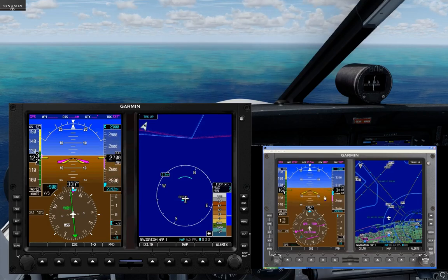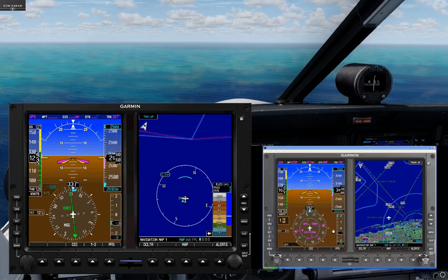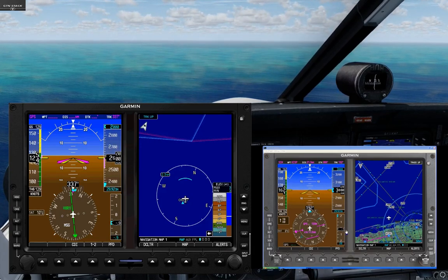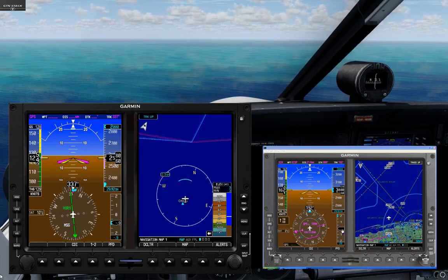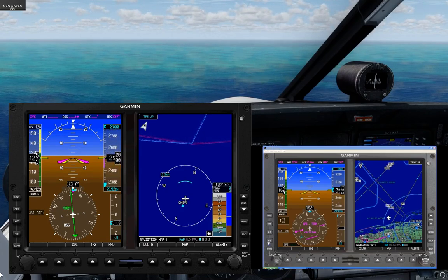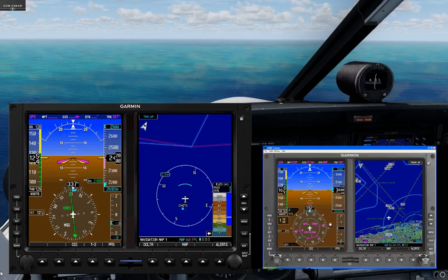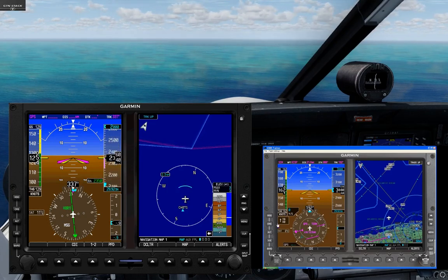There comes our altitude pre-select. Here comes our vertical speed slowly leveling out. It'll disappear back when it becomes 0, and the numeric presentation disappears, and here we are. We can now, if we wish, select vertical speed, push to sync. We'll sync whatever the current vertical speed is, and that's basic climbs and descents.